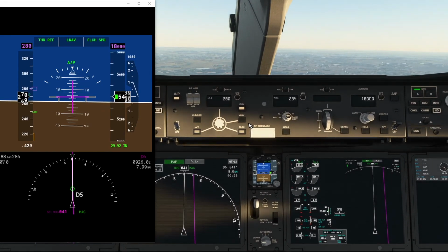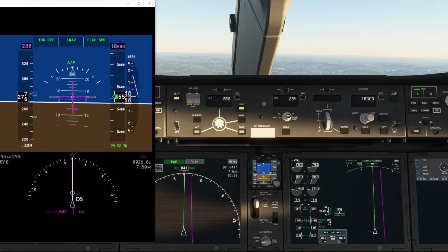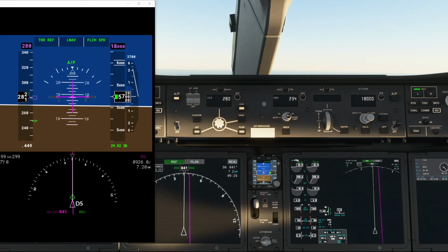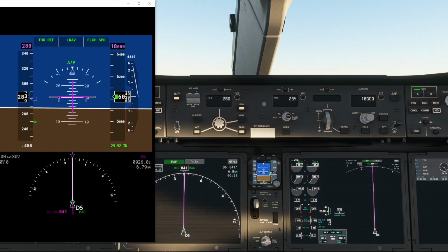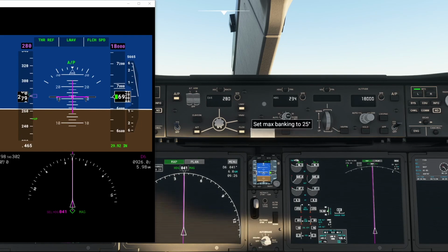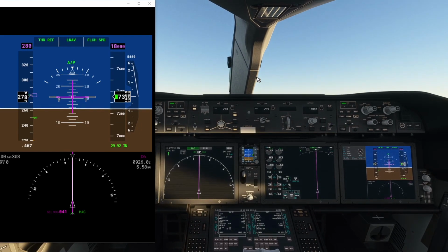And there you have it, guys. That's a quick introduction to takeoff in the 787. Points worth mentioning are that I'd say it's probably around 60% similar to real life. On takeoff, some of the pitch modes, the flight modes, enunciations, and the actual behavior of the aircraft are a little bit far off. We know this isn't a study level model, it's not the PMDG, or the fly-by-wire A320. So guys, take it with a pinch of salt, but that is a safe way to get airborne